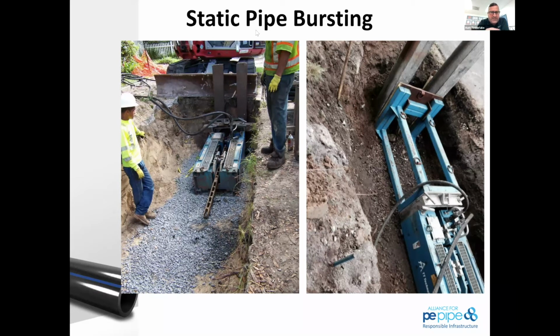And you see the rods, this is probably during the rod payout process. So you see the rod that's going in the center of the machine, and that's going to get pushed out through the existing rod. On the left, that cage you see at the end of the installation is often put in so that the head can come in and land in that cage, the head can be cut off and removed, and then you basically end up with your new flush end.